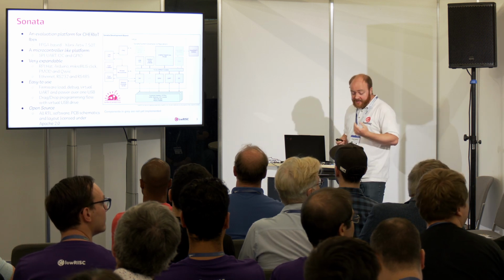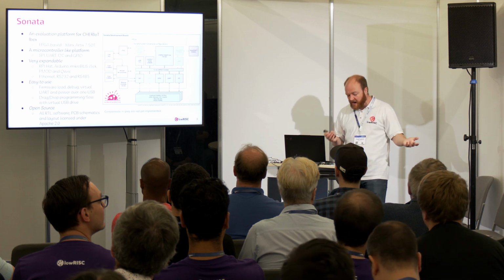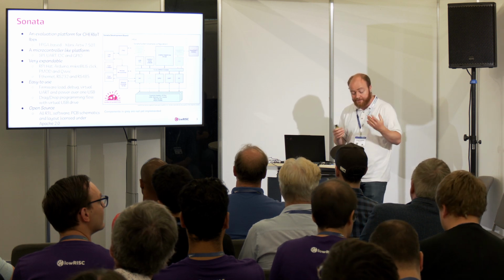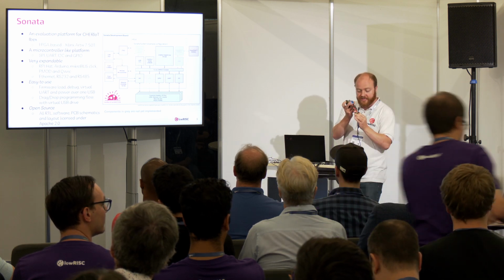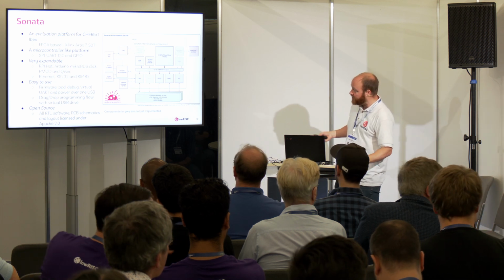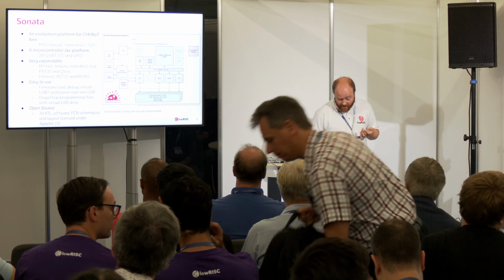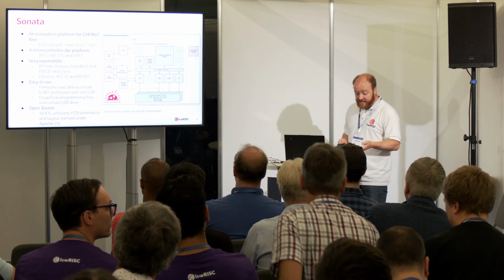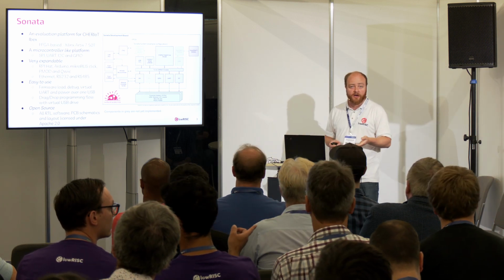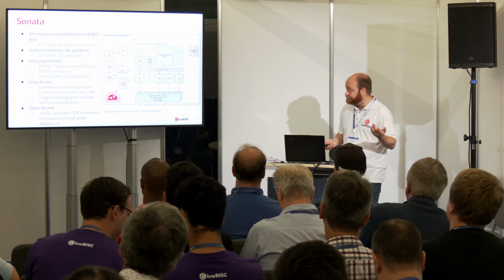And we've designed it to be as easy to use as possible. You've got all of your firmware load, all of your debug, access to virtual UART, power, and what have you over your single USB-C. And the programming method is this drag-drop programming flow you may have encountered with things like ARM Mbed or the Raspberry Pi RP2040. It appears as a virtual USB drive on your computer. You build a firmware file, you copy it onto the drive, and away you go.